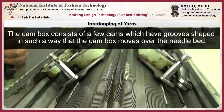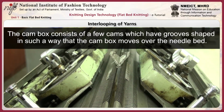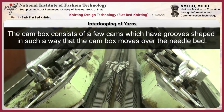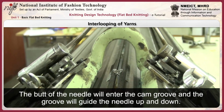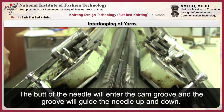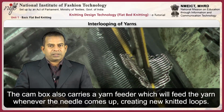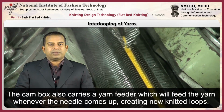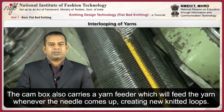The cam box consists of a few cams which have grooves shaped in such a way that if the cam box moves over the needle bed, the butt of the needle will enter the cam groove and the groove will guide the needle up and down. The cam box also carries a yarn feeder which will feed the yarn whenever the needle comes up, creating knitted loops.